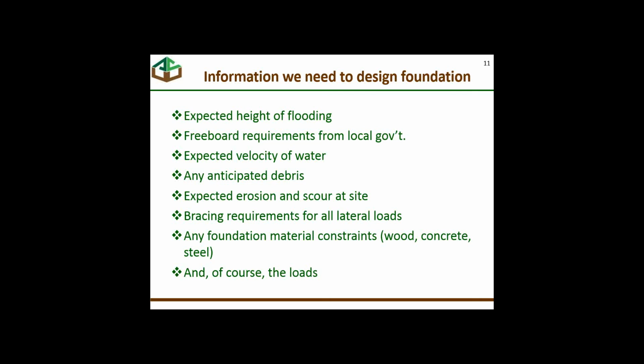There are frequently bracing requirements for lateral loads, certainly from wind, sometimes from flood, sometimes from earthquake, sometimes by the owner, because the bracing required for a lateral load might be more of a serviceability issue in terms of motion perception than it is a problem of a P-delta effect or the building being pushed over too far. But however it comes about, there are bracing requirements most often.